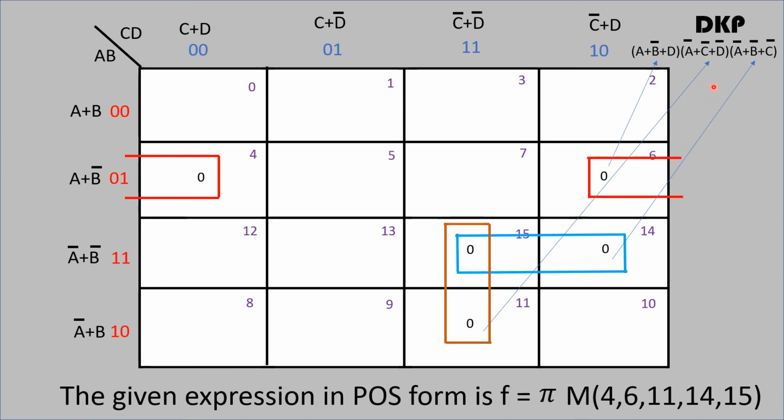Here you have to use 12 inputs, and in the previous case, that is in SOP form, we have to use only 9 inputs. Therefore, using SOP is economical here compared to POS. For POS we are using 12 inputs. Therefore, we can go for SOP for implementation.